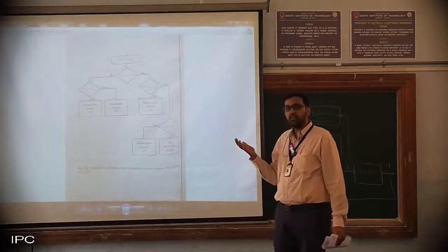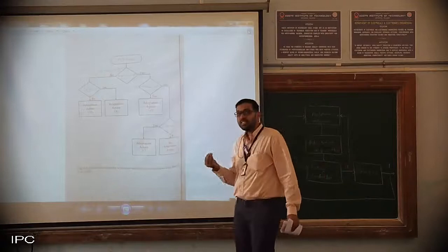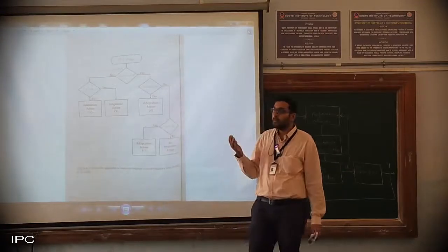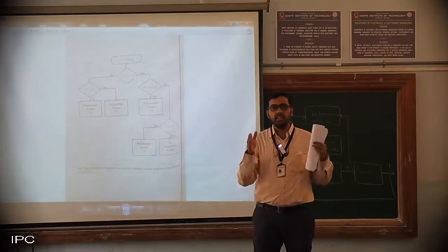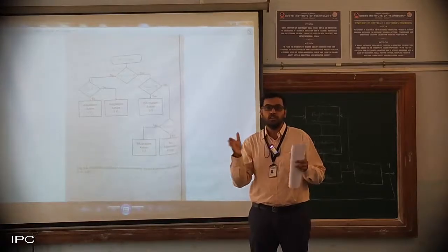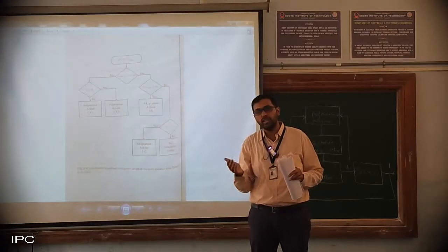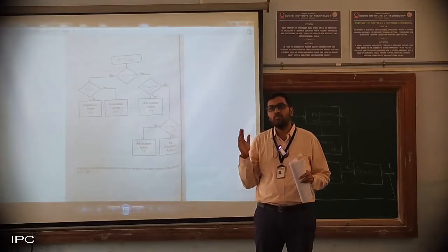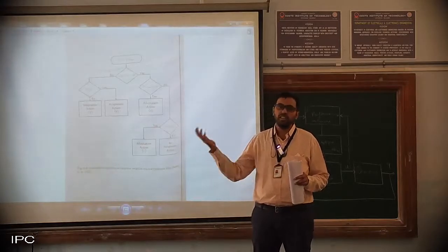There is one more method wherein the membership functions are tuned. For example, let us say we have triangular functions, and temperature ranges over low, medium and high. The low range starts from 0 degrees to 10 degrees, the medium range from 8 degrees to 20 degrees, and the high range from 15 degrees to 30 degrees, let us say.